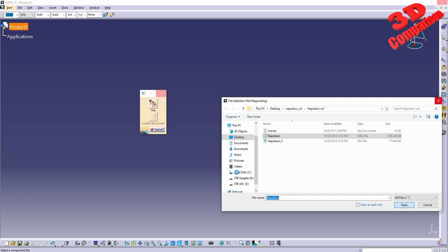And this is actually the only method that can enable textures within CATIA. And textures are really important for cultural heritage. Even though CATIA is mostly used for mechanical and industrial applications, we can make use of various elements even within cultural heritage. So we're going to see that this will now load. This will take a little bit more time since this will be a WRL, because now CATIA also has to open that geometry, and that will be linked to the unwrapped texture that we just saw before. It will take a little bit more processing time.